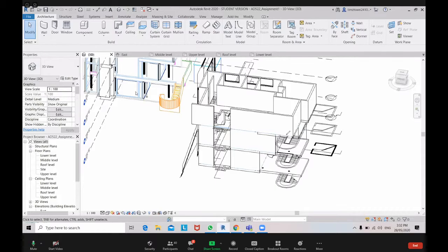So how to model a railing? Basically, you just need to draw a wall similar to this one and make it connected. I mean, make it a full wall from this level to the upper one, like you did for other walls. Try to do that first. Yeah, you can go to the middle, yeah. So, this part, basically try to model a wall.